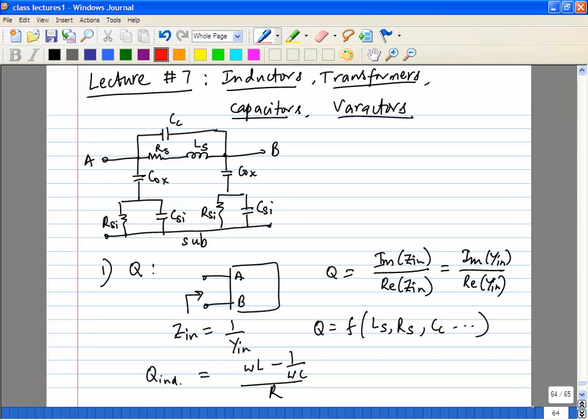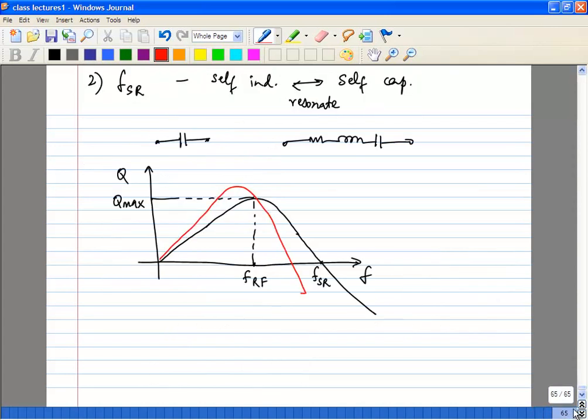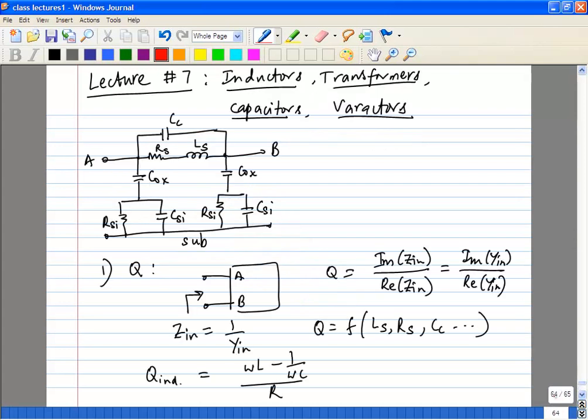Okay, we are going to come to that next. I quickly mentioned that last week, but the next thing we are going to look at is what is called a ground shield. If you see, the losses happen through RSI because of magnetic fields causing eddy currents to flow through the low resistivity substrate. So what can you do if you actually have a metal plate between the inductor and the substrate?